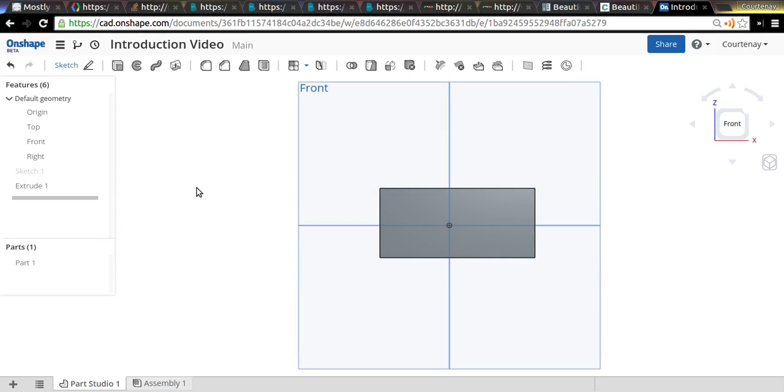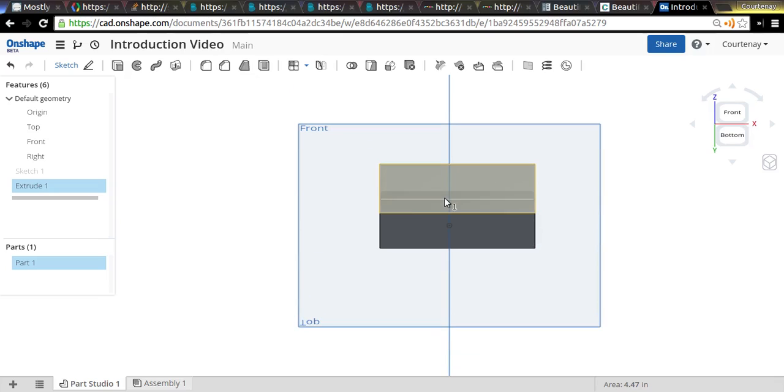So now that we have a shape, now we've got all kinds of options. So now I can have the extrude selected and do all kinds of things with it. So this fillet and chamfer seem to be about the edges. So if I click this edge, oh, I've got something else selected. See, I've got a 2 on my mouse key there. That tells me that I've selected 2 things and I don't know what they are. So I can just click over in some white space, and then that'll be back to a 1, which tells me I've just selected this edge.